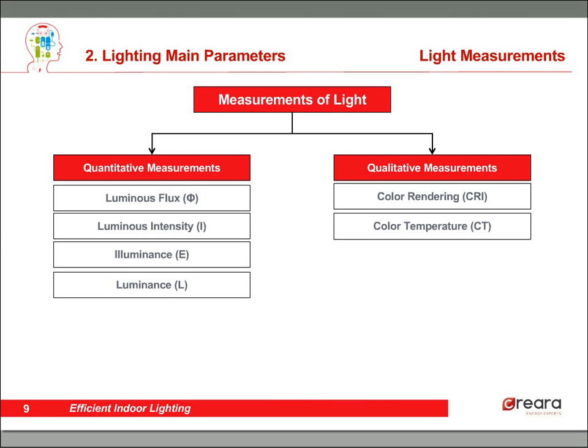Okay, here we're going to stop because it's really important to differentiate flux and power. The power is the electricity, the electrical energy absorbed by a lamp in watts. The flux is the capacity of the lamp in lumens. The rate between these two, between lumens and watts, is the energy efficiency of the lamp.